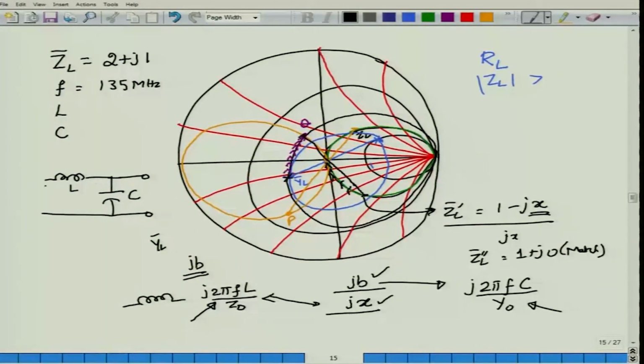So this is your matching network. Unfortunately, this matching network that we have obtained is not broadband, because if you start looking at its frequency response, at the desired frequency it would peak at the desired value. But what happens when the frequency is very large? Then this inductance will have a reactance which would be very large, the capacitive reactance shorts out, this becomes an open circuit, and the response actually drops down to 0. On the other side it will not drop down to 0, it would be slightly asymmetric, because at very low frequencies the inductor will act like a short circuit and the capacitor will act like an open circuit. So this is the frequency response of this particular matching network.